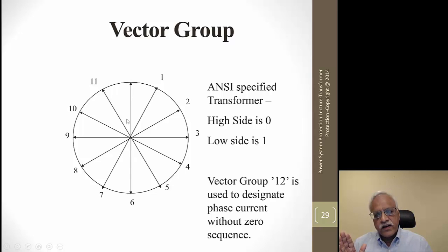And then if it is YY0, that is a 2-winding transformer, it is the same as this. There is no phase shift. If the polarity is reversed, it becomes YY6. Similarly, for example Y1, if you change the polarities of the windings, then it can become Y7. That means it is lagging the reference winding by 210 degrees.